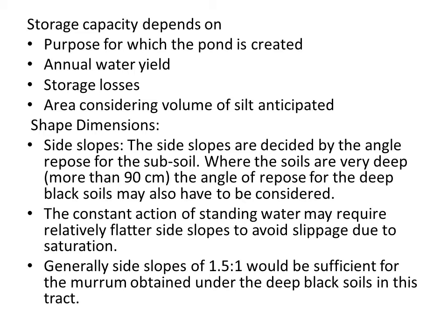The side slopes are decided by the angle of repose for the subsoil. Where the soils are very deep, the angle of repose for the deep black soils may also have to be considered. So the side slopes mainly depend on the angle of repose of the subsoil, and if it is deep or more than 90 centimeter, the angle of repose for the deep black soils may also have to be considered.